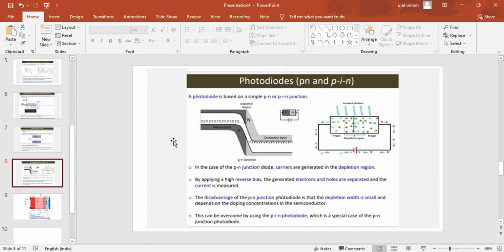In such a photodiode, when light falls onto it, especially inside the depletion region, there is excitation of electrons and holes. But these electrons and holes are excited in two separate regions, one in the p side and one in the n side, and they can't cross the depletion region and recombine because of the immobile charge carriers, or the electric field already in place.